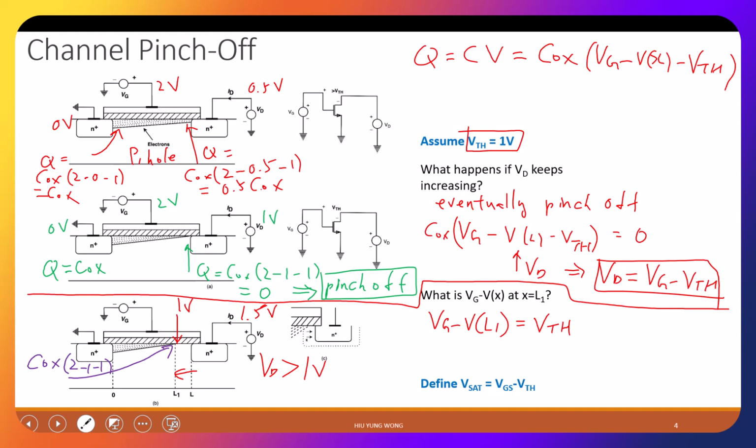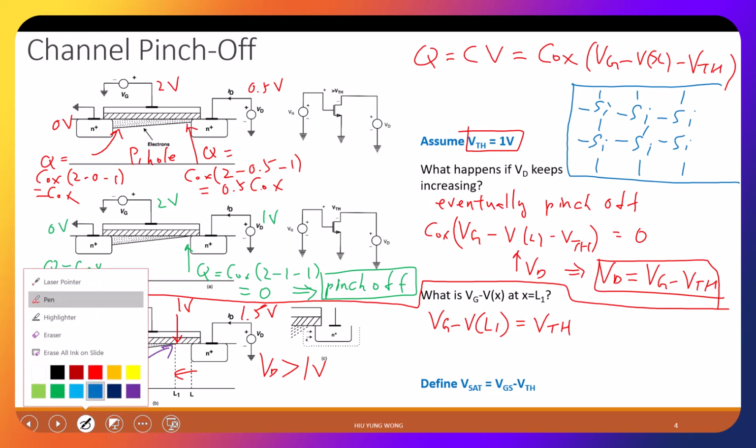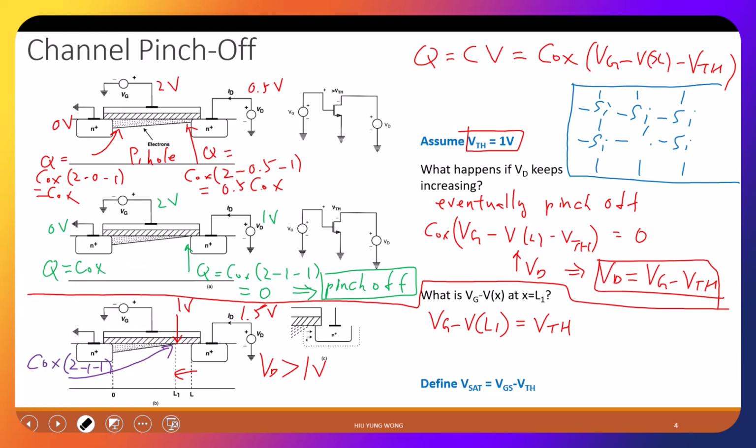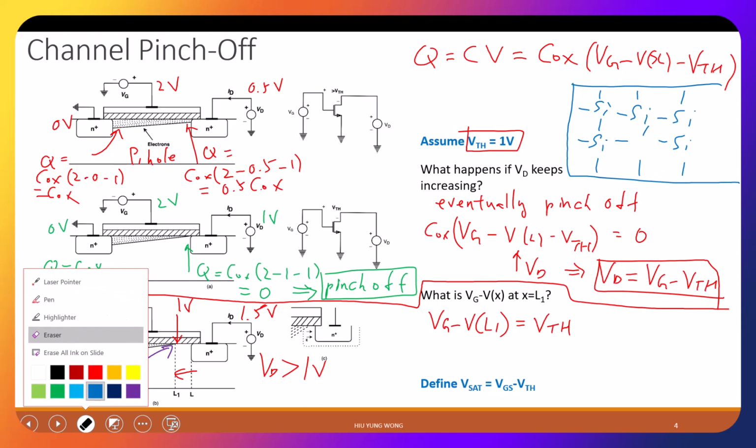The depletion charge, so it's good to review this one more time. How do we dope a silicon? A simplified view, if you have learned that before. You have a silicon lattice. These are the atoms. You have a lot of silicon atoms. Are you okay with this picture? So how do we dope it? Of course, this is a simplified view. What we do is, for example, we replace this silicon by a boron.